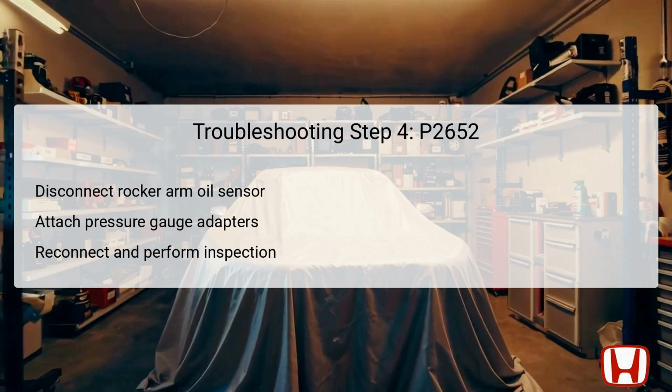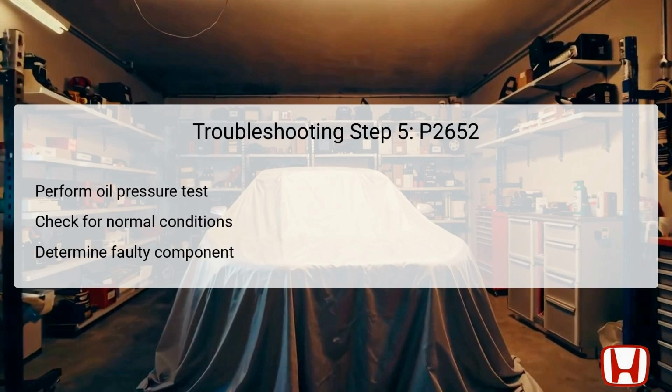Once all connections are secure, it's time to reconnect the rocker arm oil pressure sensor connector and proceed with the confirmation procedure. Monitoring actual pressure readings will now allow you to gauge whether the sensor or the control valve is the source of the issue. This step is crucial for facilitating an accurate diagnosis of the DTC being addressed. Performing the oil pressure test on the rocker arm assembly helps confirm whether the readings are within normal parameters.